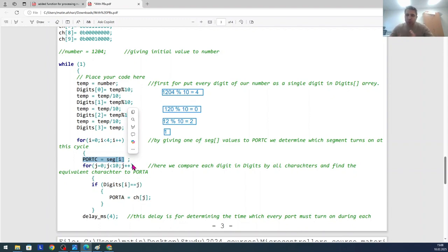You need to just sync and follow the I and J here, so that we have the second digit connected to the 5 volt, and now we have to connect the port A to the negative side of the LEDs to decide which number should be shown there.